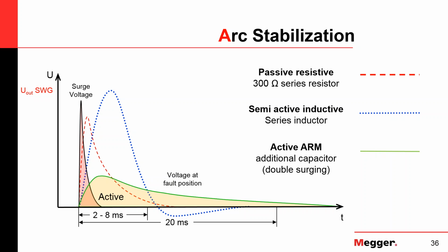The reason is you want to maximize the chance that one of the radar pulses is actually hitting that arc when it's standing there, when it's burning there, for only a few milliseconds, and so you can actually see where the fault occurs. These TDRs that are involved in fault location are not your typical handheld TDRs.